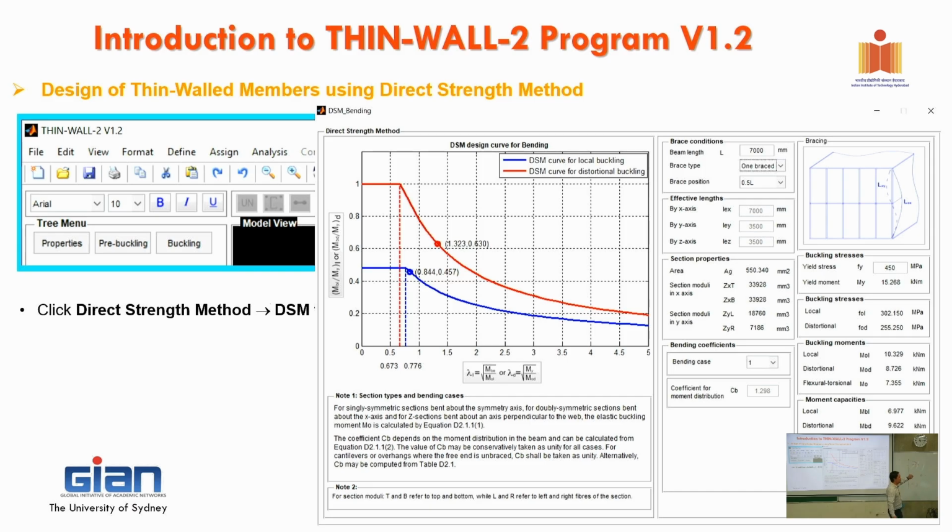We forget about the normal stress caused by the moment gradient and just input the shear flow. So we can work around to isolate shear without the influence of bending. That's why in shear you can get the minimum point. But with finite element analysis, using Abaqus or whatever, you can't get it because it's in equilibrium. It is a product of the moment gradient, so you can't separate that. The only way you can separate is using finite strip.